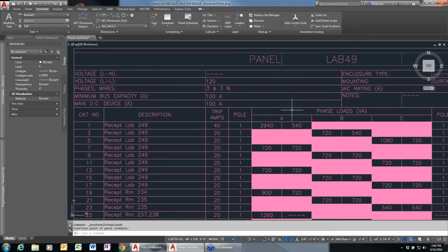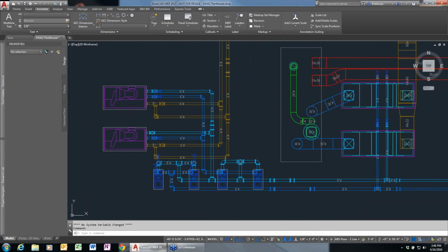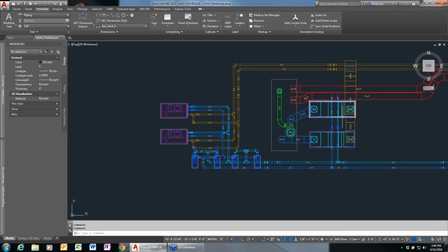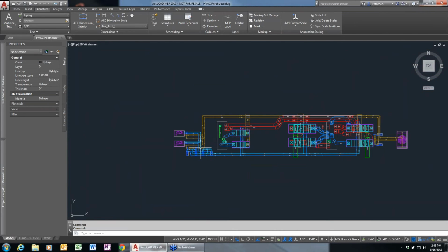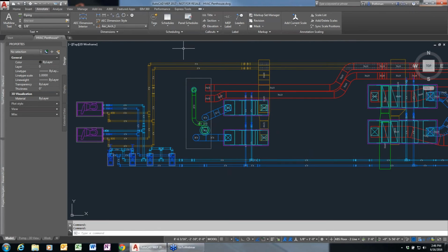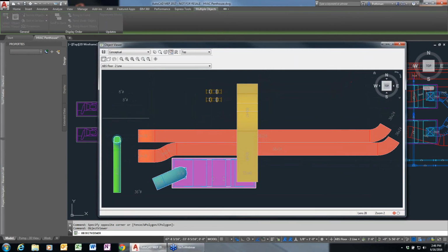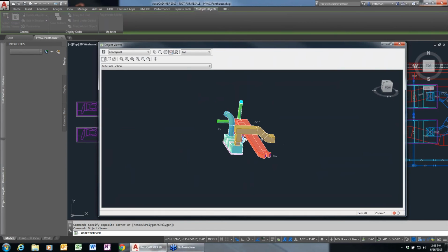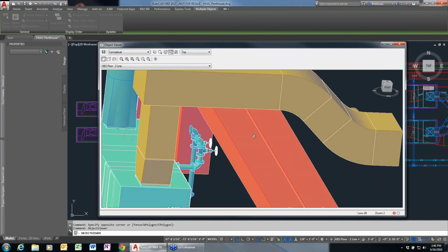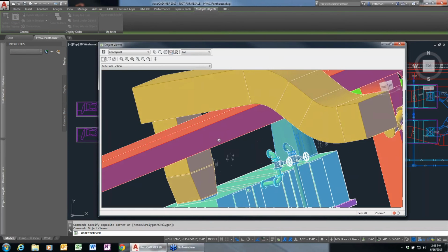And then the last thing I want to show real quick is an example of doing sections. So I said I was going to go back to my HVAC floor plan. When you have something like this, it may be good enough that I can just select a few objects and send them to my object viewer to see if things are hitting one another. You can see that in this case, the duct is just underneath the other duct, just clearing it, right? So that's good.